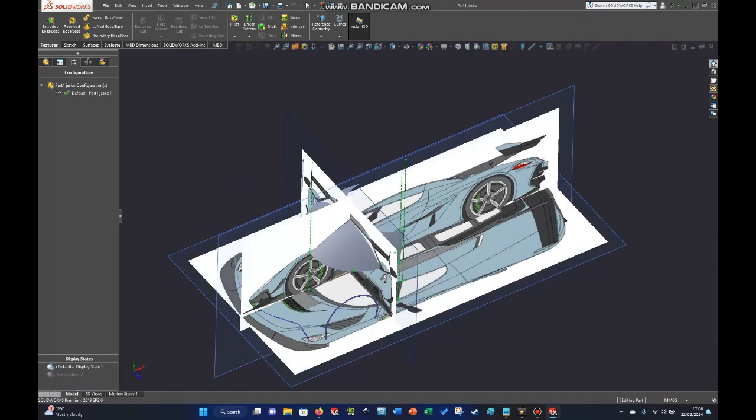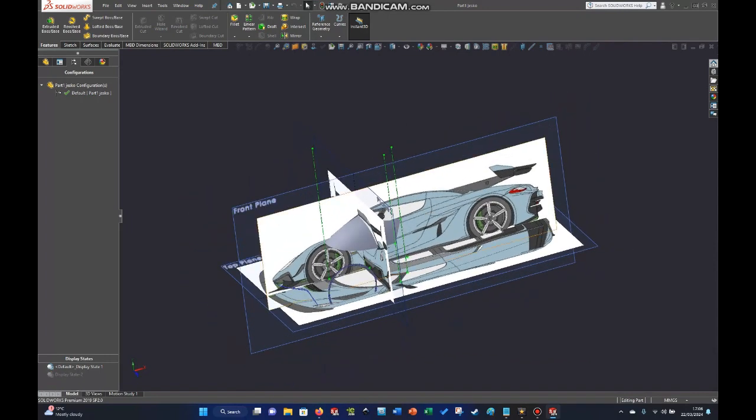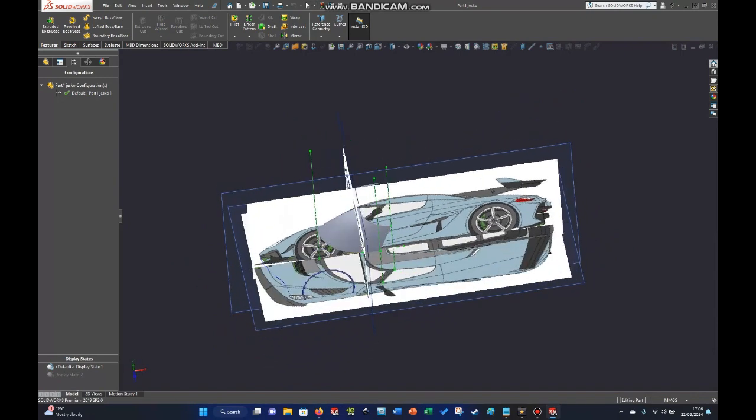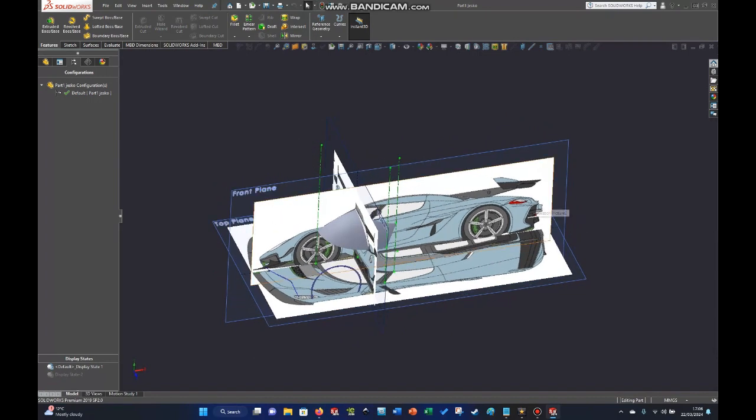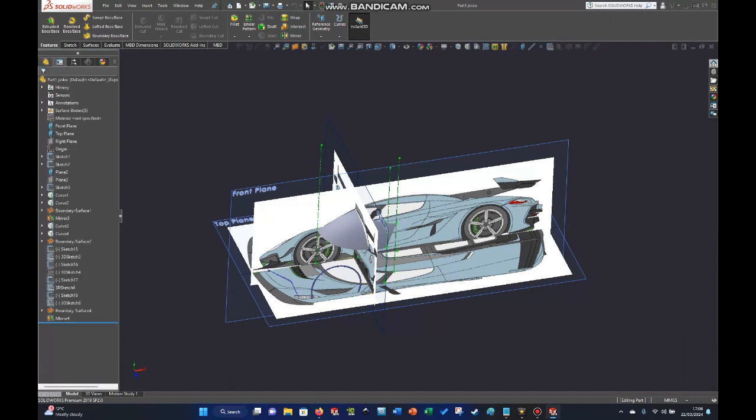What I want to do is bring this side surface all the way to the back, and to do that I need to get that point in the back here. Of course, I need to create this curvature first, the rear curvature, and for that I need to bring up the rear view image. So I'm going to go to the feature manager design tree and find that plane that we created before. It's plane 3. We can always rename your planes if you want to.